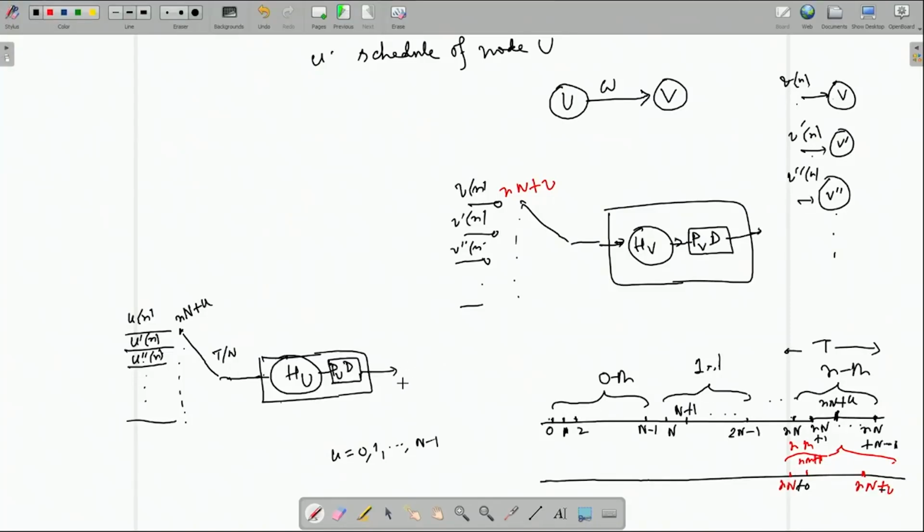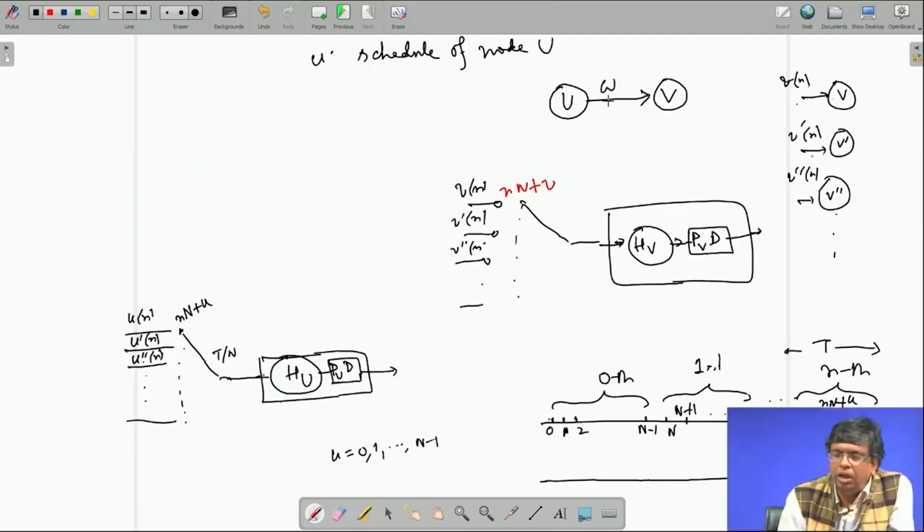How much delay I should have. Originally, I had W number of input delays, input cycle, because that is what is given with respect to input cycle. Folding is my creation, but this DFG is given in terms of original input. Okay, I have got W number of delays, all right. So, that means in the timing diagram, I can erase this timing diagram down, or maybe I draw here separately.